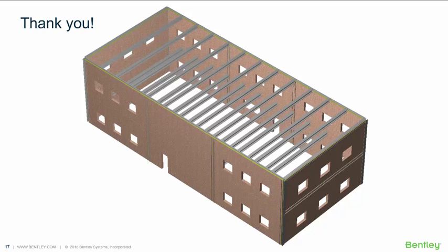And I'll mesh the structure. I won't analyze it, I'll mesh it, and then I'll take a look at how the mesh turned out. I'll look for any highly skewed elements or any kind of distorted elements. And from there, I usually won't even reduce the mesh size. What I'll normally do is increase the node density factor, I believe it's called, in RAM Frame. It's defaulted to 1, and it's an integer value that can really go as high as you want, I think. And what that does is it places more nodes in areas where the mesh tends to get congested.